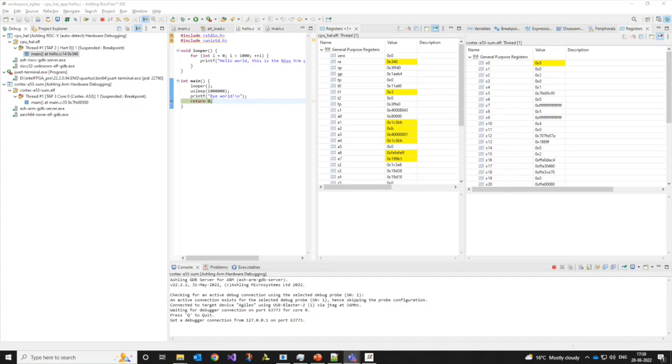Okay, this question is a matter of migrating your software designs from Nios 2 to Nios V. The question is specifically, how can I port my Nios 2 application to Nios V? Nios V supports the same bare metal hardware abstraction layer as Nios 2, and similar RTOSes. Our intention was to make migration or porting easier from Nios 2 to Nios V. So that's why we continue that on Nios V.